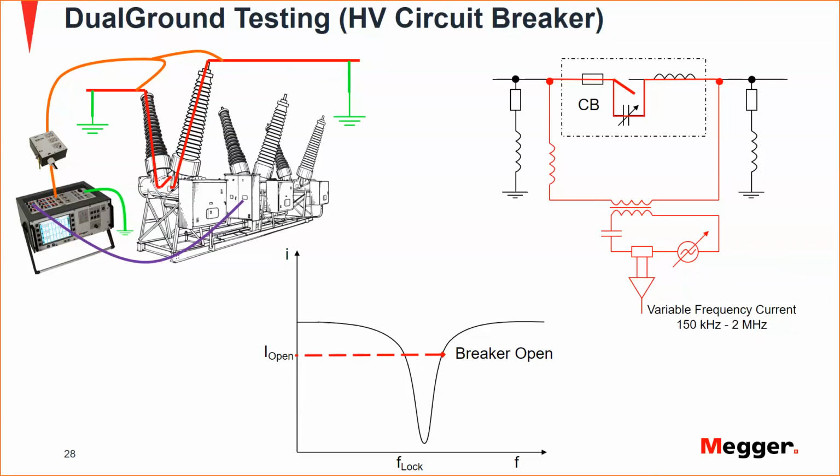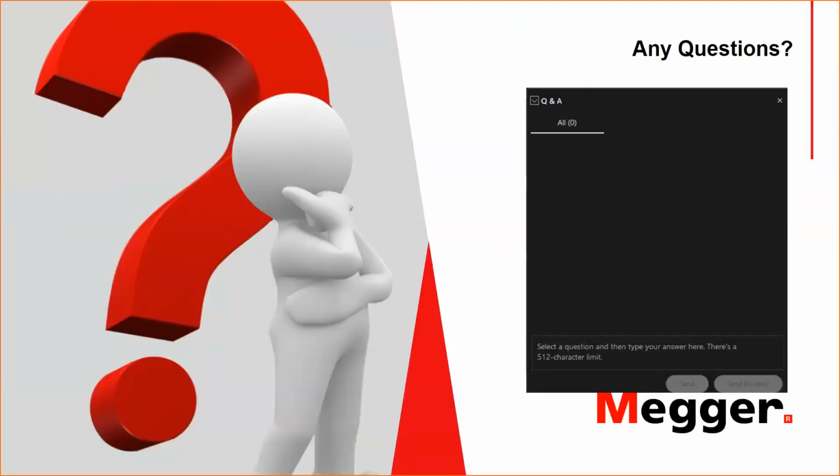Okay, so next question. Is the VIDAR test a routinely recommended test? What he's referring to in this question is, I believe, the vacuum interrupter dielectric absorption test, or basically a high-pot test to the vacuum bottle.